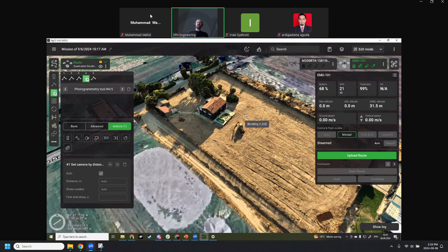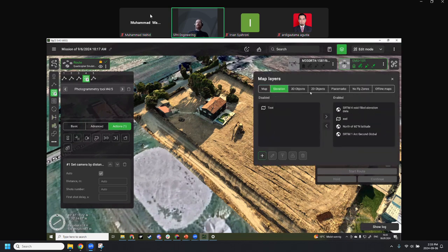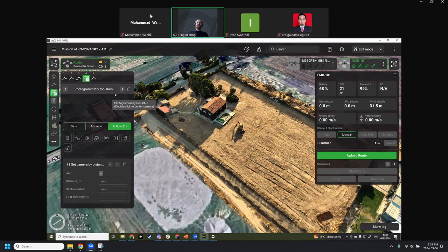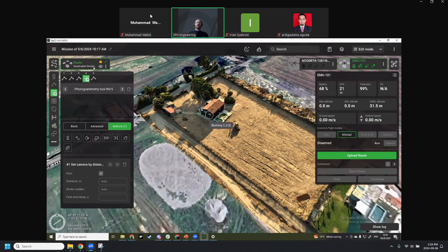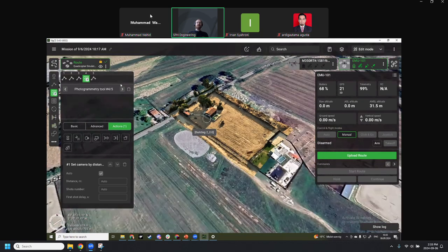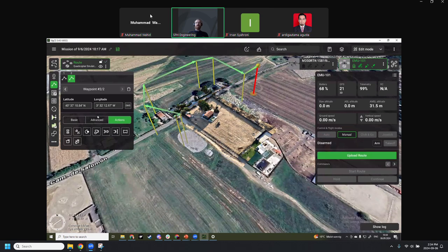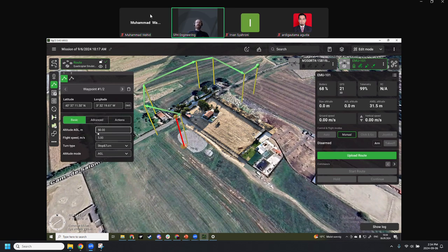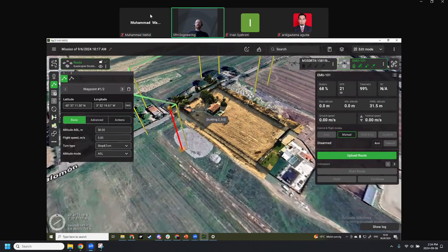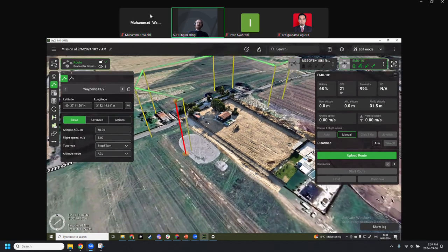But for terrain following, I really recommend using them in the elevation tab instead, because 3D objects are seen as obstacles, and depending on the model configuration, it might not do what you need. Like, for example, with this model, as you can see, the waypoint is at a 50-meter altitude, which is a lot higher than the houses displayed.